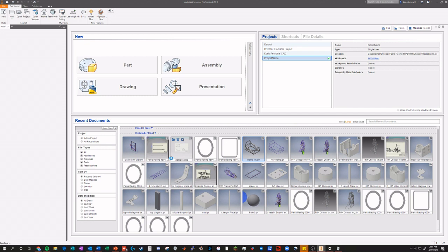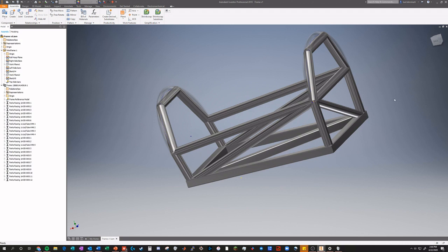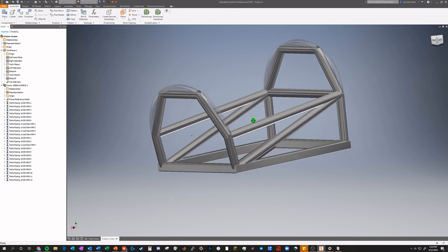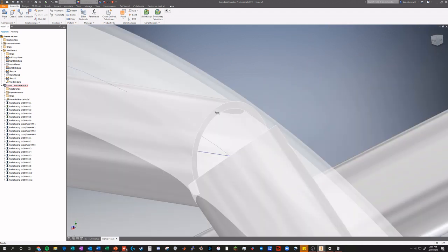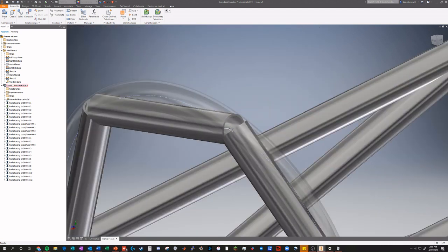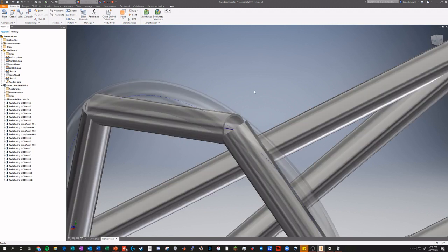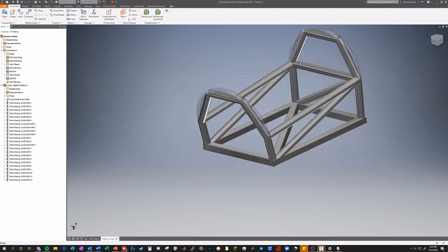Remember we talked about how we'd have to put in the straight lines for it to work. That is because this is actually a beam model. So what that means is it's not actually splitting this geometry into individual little mesh. It's actually going to treat the entire thing like a beam, and it's going to propagate the cross-sectional areas the same way you would in a statics or a mechanics of solids class. But it's obviously going to do those calculations in 3 dimensions and for whatever loads you apply.